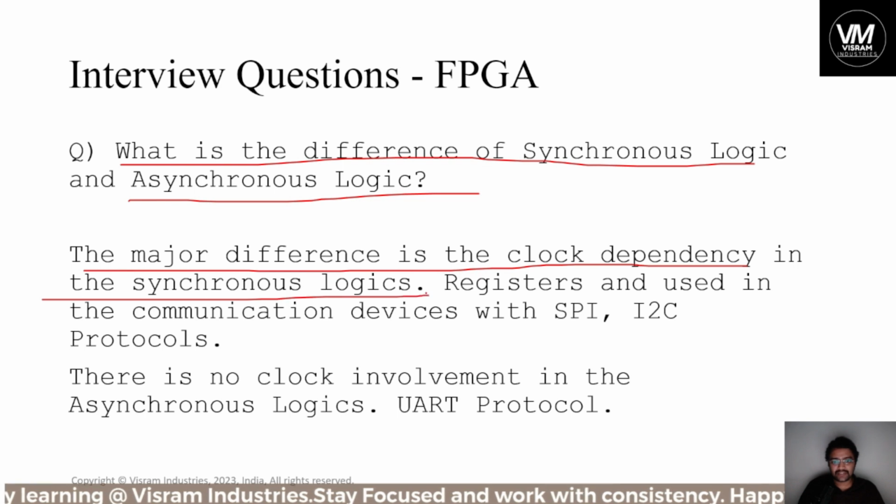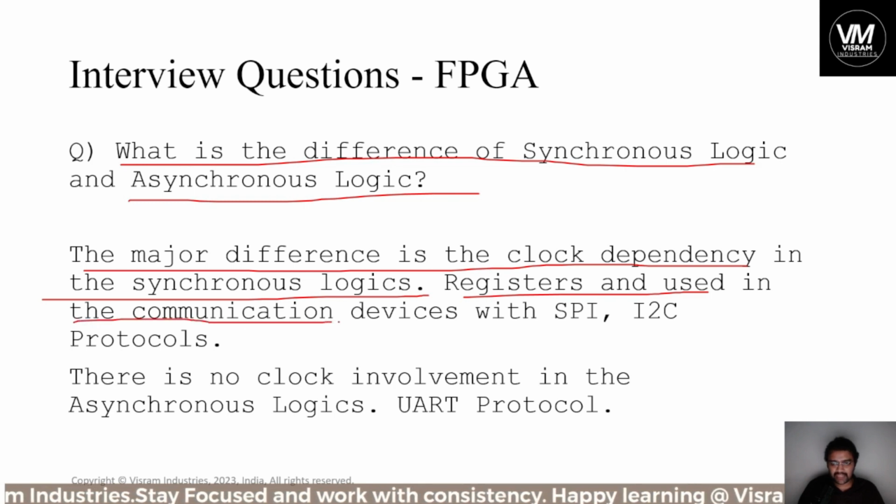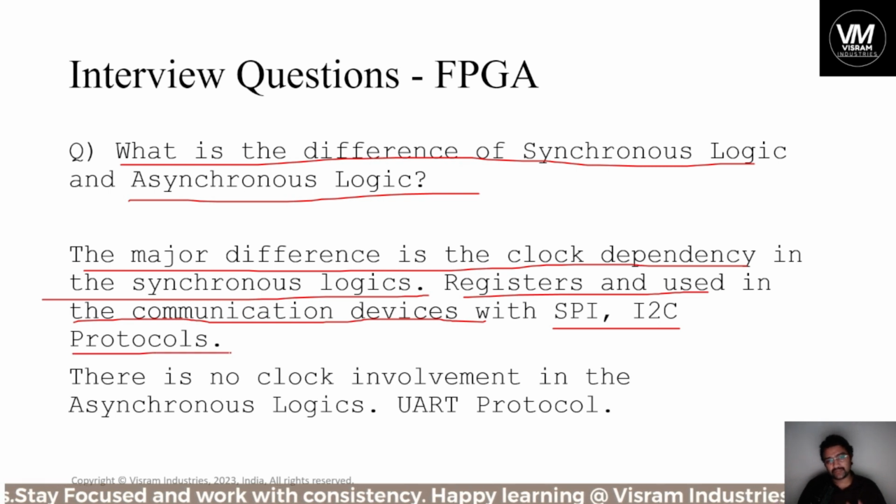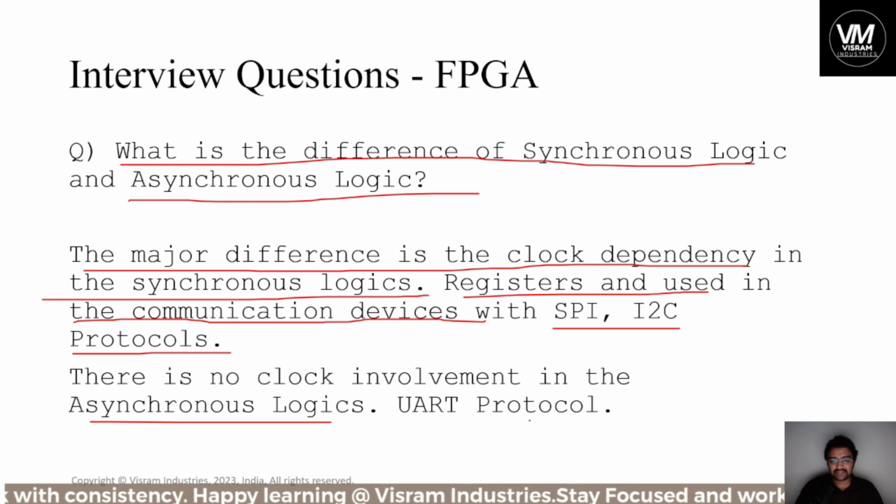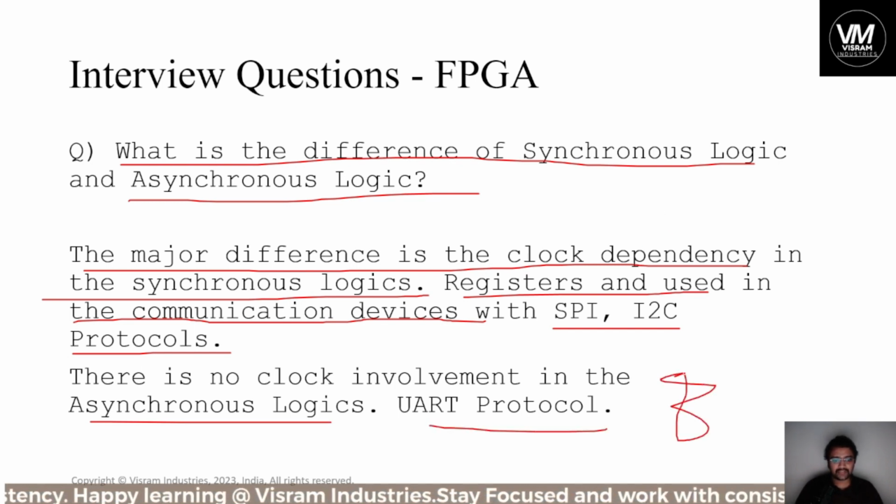In the synchronous logics, registers are used in the communication devices with SPI and I2C protocols. So with these protocols, synchronous logic design should be there, like registers. And for the asynchronous, UART protocol is an asynchronous protocol, so it can shift from different registers or different sets of instructions. There is no clock involvement in asynchronous logic. Okay.